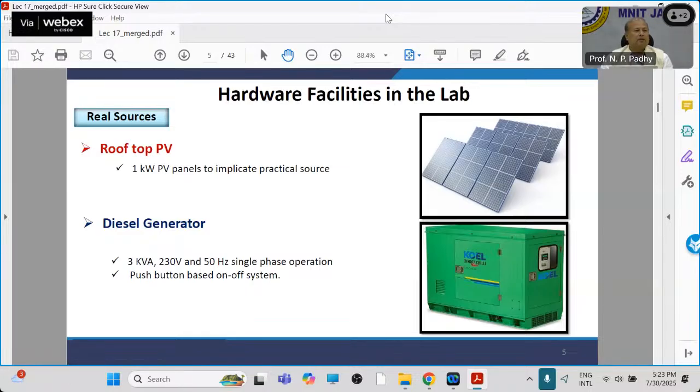And then a very interesting part. We thought that when you are simulating a smart grid, either DC or AC, it must have a diesel generator, because in this country DG is very common. If you do any study without taking a diesel generator, somewhere we are not bringing clarity to Indian smart grids. So I forcefully introduced a diesel generator of 3 kVA capacity. Now tell me, what are the sources? 5 kilowatt of PV, and then 2.2 kilowatt of wind, so 7.2, and then this is 3.